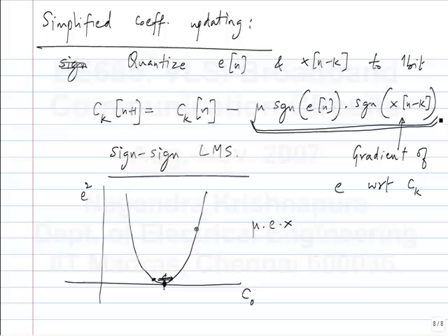But let's say one of the things in which you need equalization, it's not a communication link, but it is very much similar to what we discussed, is a hard disk drive. A hard disk drive stores bits on a magnetized disk. As you pack more and more bits, the area available for each bit is very small. So the magnetic field of one particular bit influences other bits. So you have intersymbol interference exactly like what we have with a low pass channel.